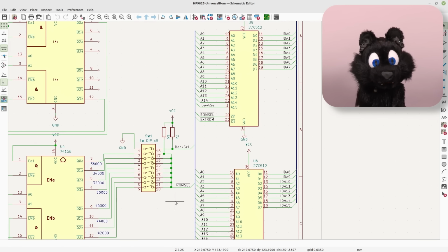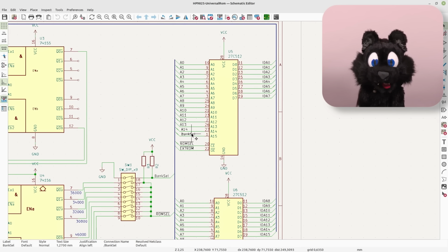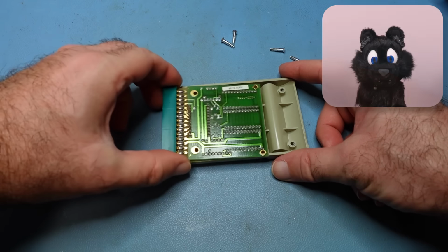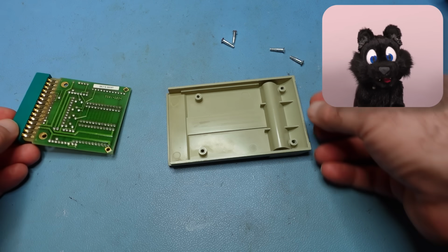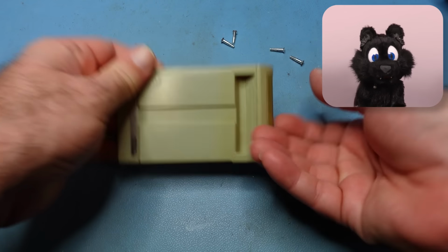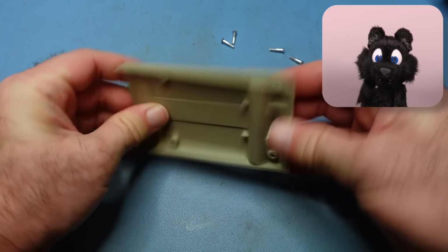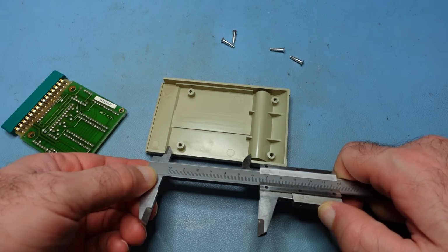Oh, and since I have more than double of what I need in space, I can use one bit of the ROM address space to have a bank selection, allowing two sets of ROM images in the EEPROMs without reprogramming them. Now that minimalist circuitry still needs to fit into that ROM drawer of the 9825A, which has even less space for it than you'd think, because the pull handle takes up a chunk on the inside.